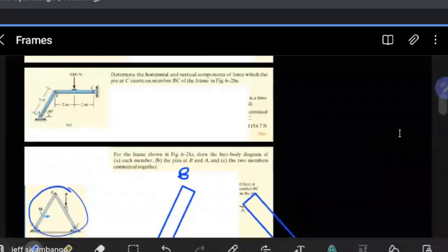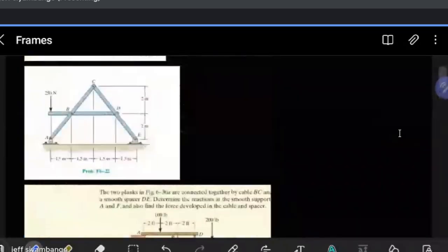Now, what this is actually saying, it doesn't mean that if a member, like the way this one is, is actually all the way from here up to the very end there. So when drawing this, you don't say, okay, since there is something here, when I am disassembling this, I should only go up to the point B and then end there. This would be wrong. Instead, you have to start from here, going all the way up to the very end there. But you're only looking for the outline when it comes to free body diagrams, so like that, and like this.